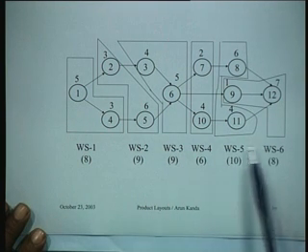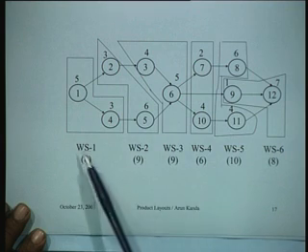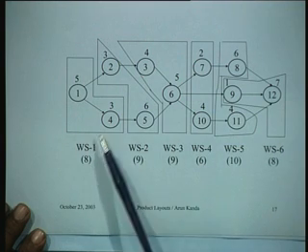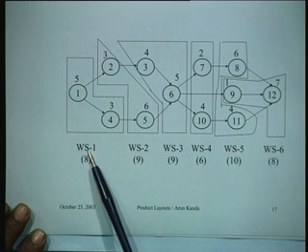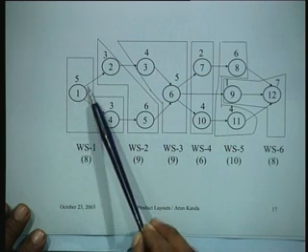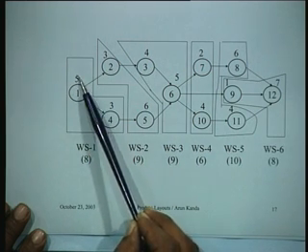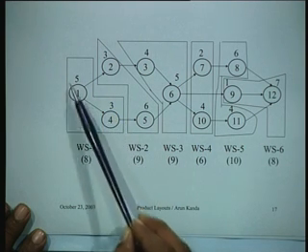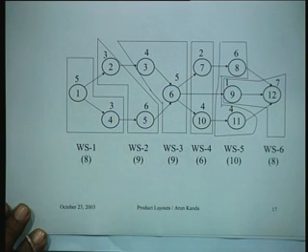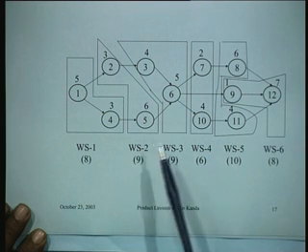So I have 6 workstations. What is a workstation? I have exactly defined what is to be done at this workstation. That means the person who is going to sit at workstation 1 will first do operation 1 and take 5 minutes, and then do operation 4, which will take 3 minutes, thereby taking a total of 8 minutes, and so on for the next operator and the next operator.